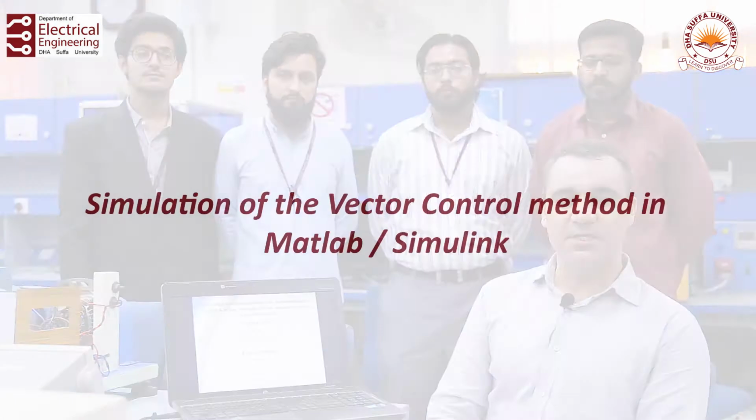And wherever a more dynamic and quick speed and torque response is needed, the vector control strategy takes precedence over other control strategies such as the volts per hertz control strategy or other control strategies that are often used to control AC machines.